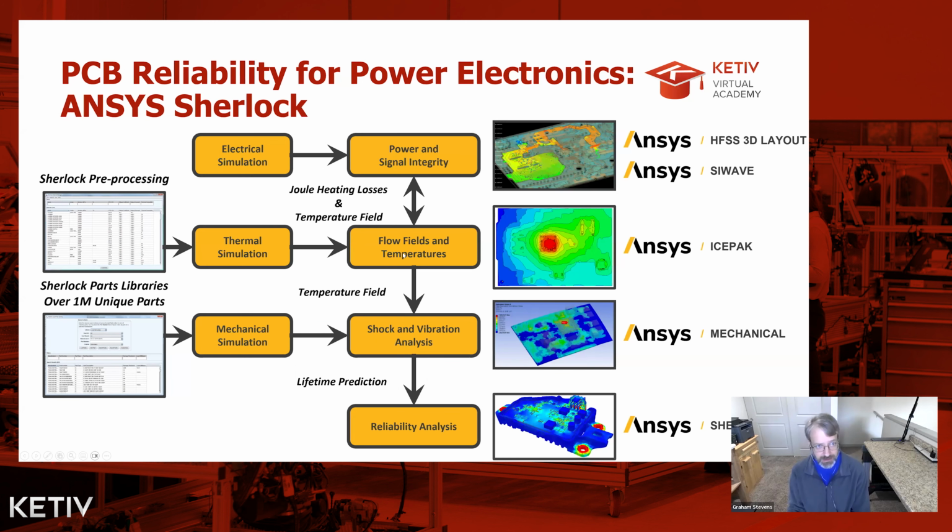And then lastly, I wanted to mention PCB reliability for power electronics. There's a package called Sherlock within the Ansys Mechanical realm that starts with a component database of your PCB board, all the resistors, all the different chips, where it has listed, basically, properties associated with reliability. And by just getting a bill of materials for your PCB board, and the layout, I can get relatively quickly a good estimate of mean time between failure for each individual component on the board,